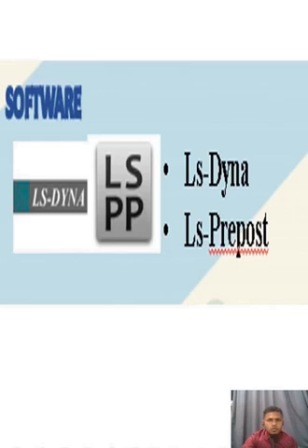LS-DYNA consists of a single executable file and is entirely command line driven. Therefore, all that is required to run LS-DYNA is a command shell, the executable, an input file, and enough free disk space to run the calculation. All input files are simple ASCII format and thus can be prepared using any text editor. Input files can also be prepared with the aid of a graphical preprocessor.